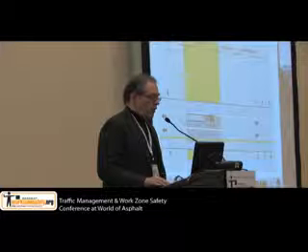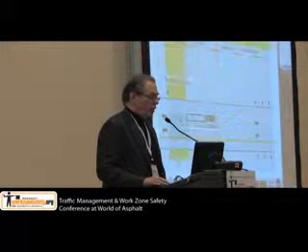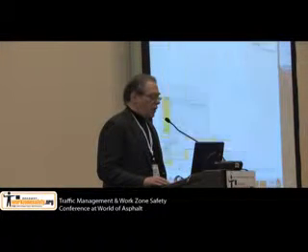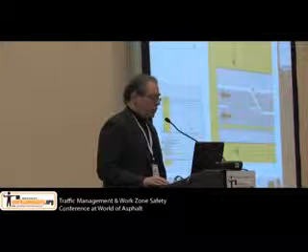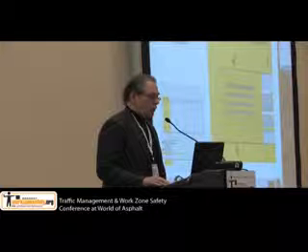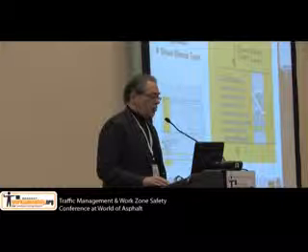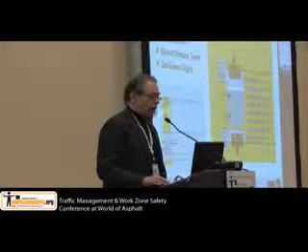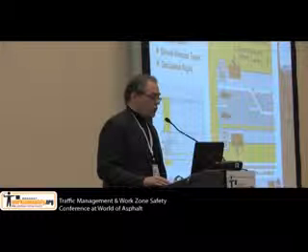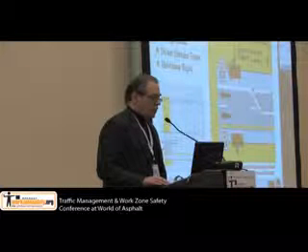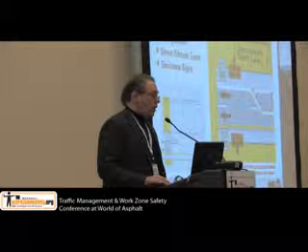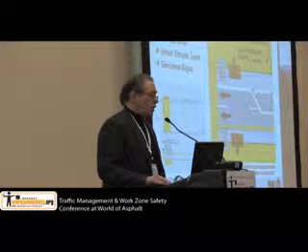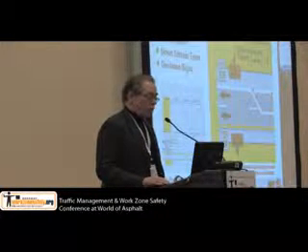And then finally we have the termination area. In the termination area, normal traffic flow resumes. Parts may include a buffer space, which is longitudinal, a downstream buffer, and guidance signs that can be used before normal speed resumes. And again, notice that we still have over here, from our original diagram, a locator objective to keep us in place where we are.